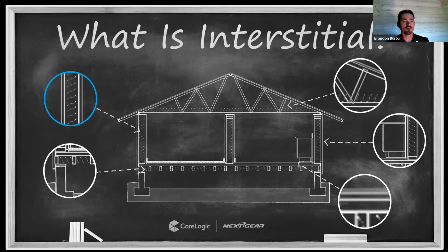And again, the reason why this conversation is so critical is because if I put an air mover in that carpeted room on the left and a dehumidifier in that room on the left, and I start circulating warm, dry air, that's not going to do a whole lot for the wall plate at the bottom of that wall if the wall plate is wet and affected, right? It's not going to do much, if anything, for the insulation in that cavity if it's wet and affected.